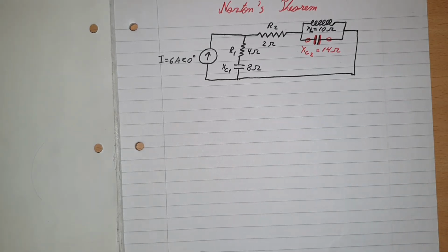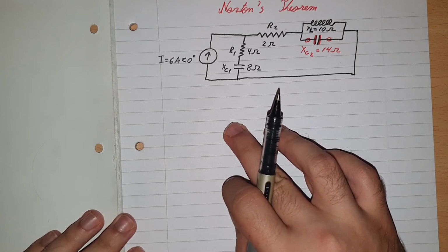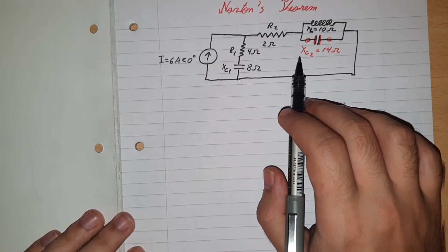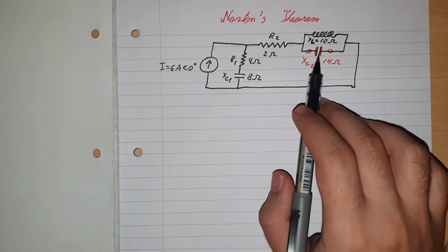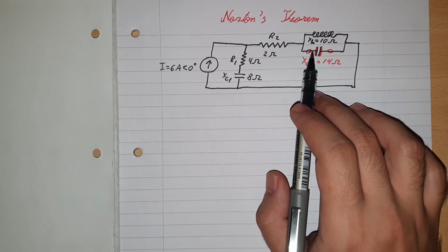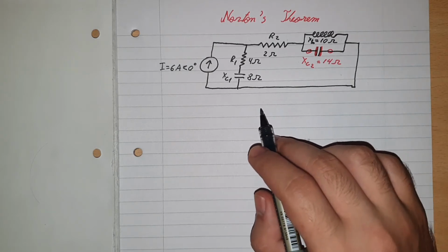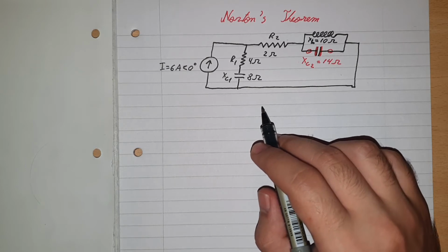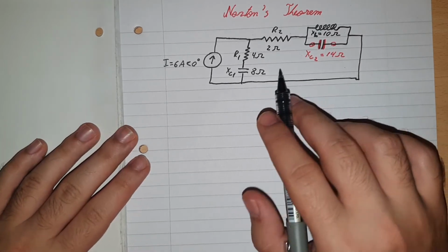Now maybe in DC you do use them to calculate an entire circuit, but here you already use them to simplify it, because again, you usually use them with potentiometers. Use Norton and Thevenin's with potentiometers, because you'll take one component as reference, and then after calculating everything, you can just plug the number of the resistance into the formula, and then you do get the answer that you want, like the voltage or the current going through it. But we won't get into this, so let's get started.